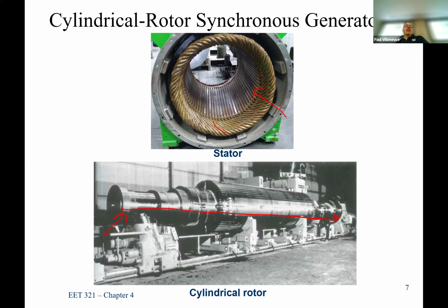So it just has to take time. They have a certain amount of time before they have to get it to spin. If you have to shut down for maintenance, it depends on the metallurgy of the machine. The manufacturer will tell you if you're going to be shut down for more than, let's say, 5 days, you've got to get it rotating.